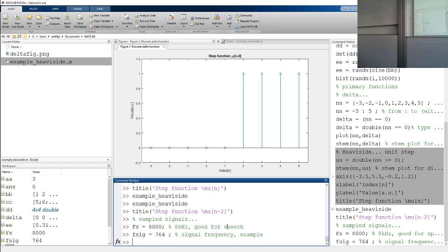Conditions, yes, there are two different ranges, 1 and 2, so either 2.4 to 3.6 or 1.8 to 2.4, to get the highest sampling rate. ADC clock frequency, okay.